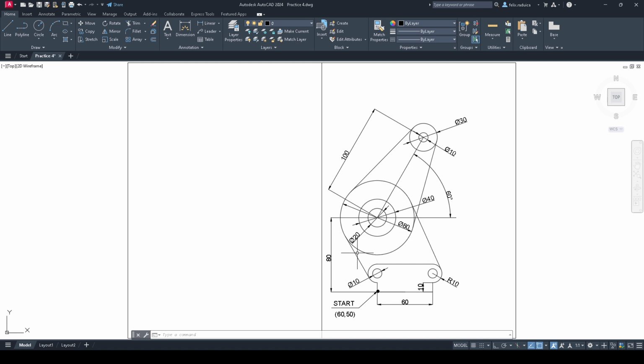Then give the tangent lines for these 2 arcs and the big circle. Then we have a line with the length and at an angle, and we draw that to pinpoint this origin of the 2 circles, and to draw the tangents so that we may finish the drawing.